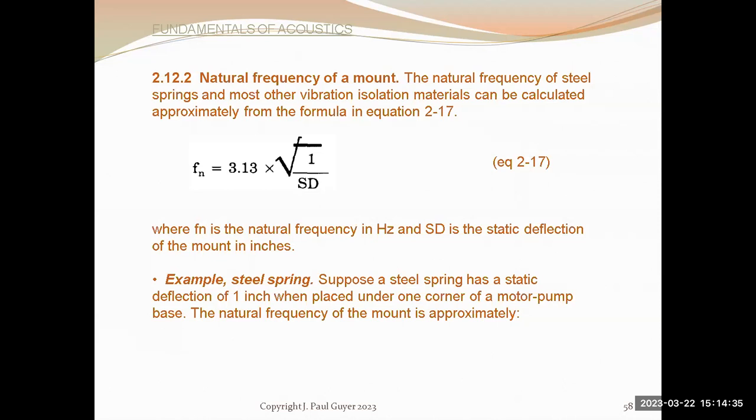Also, another common device that is used with fans and similar mechanical equipment is spring isolators. And these are little springs inside a housing, and you put 4 of them down on the floor slab, and then you set a base structure of some sort on top of these 4, or could be more, spring isolators.